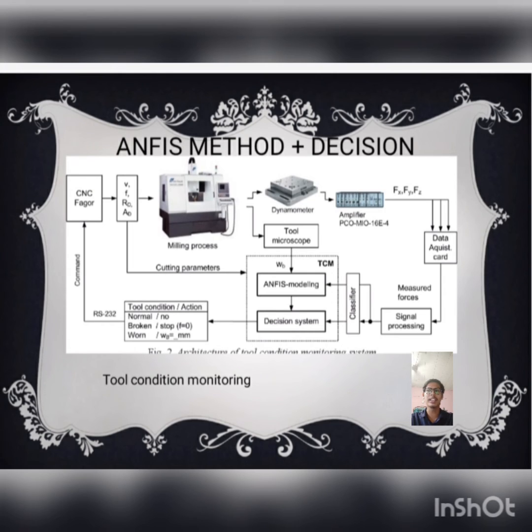The ANFIS method seeks to provide a linguistic model for the estimation of tool wear from the knowledge embedded in an artificial neural network. It uses the relationship between flank wear and the resultant cutting force to estimate tool wear. A series of experiments were conducted to determine the relationship between flank wear and cutting force, as well as cutting parameters.